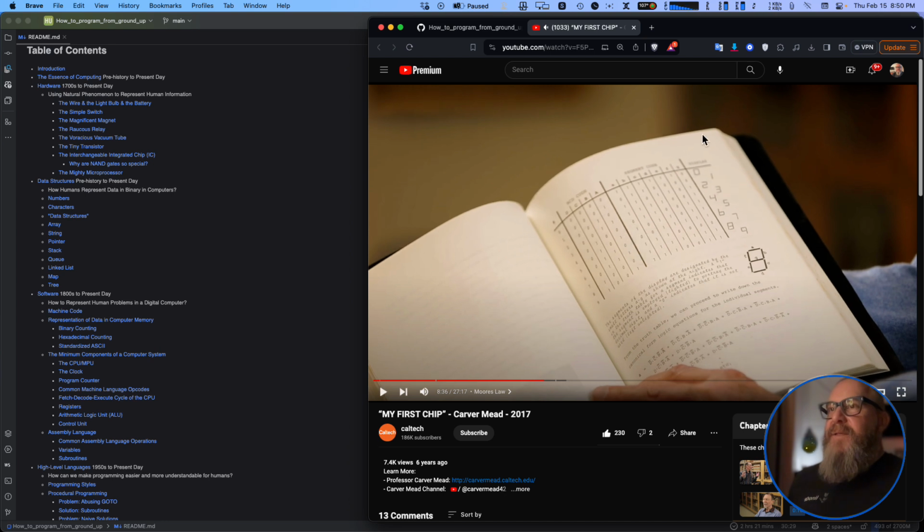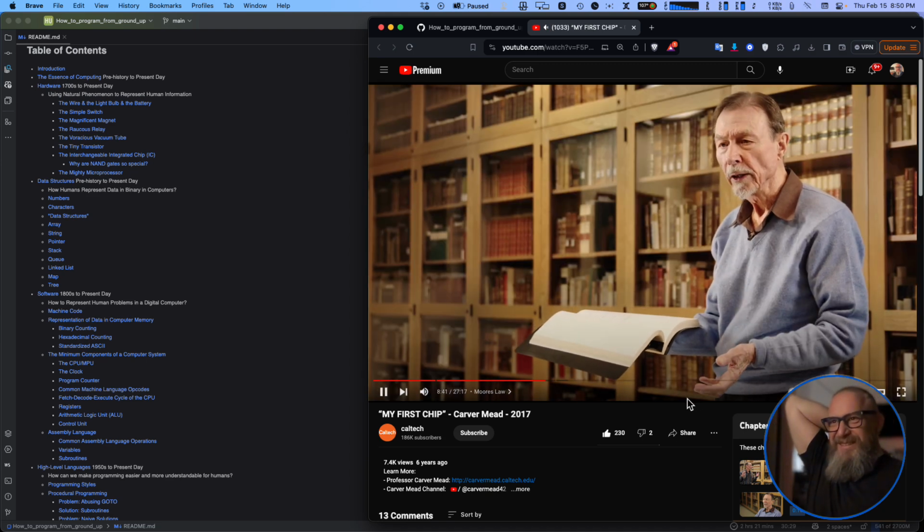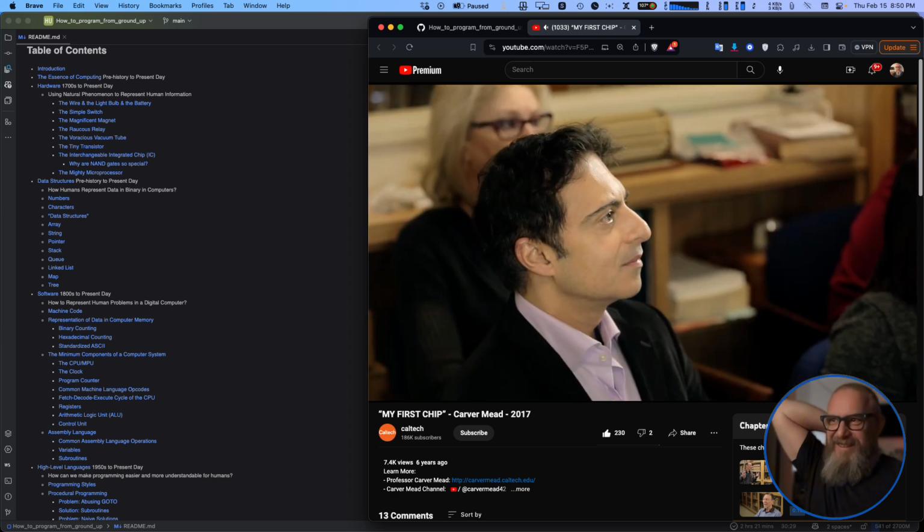So that's the same one they use in the text, and he shows the Boolean logic sequence down here for each one of the numeric values. Here it is in decimal. Here it is in BCD, binary coded decimal, for all the digits. And then here are all the different segments: segment A, segment B, segment C. Each one of these columns, and there are the numbers. That's the absolute ground training you need before you design any of these integrated circuits.